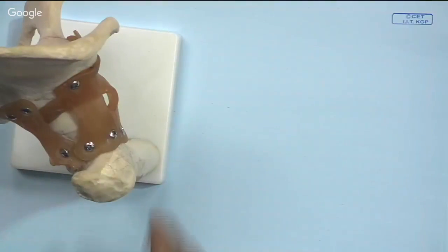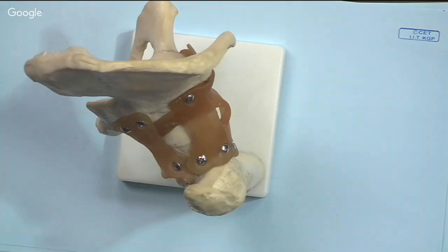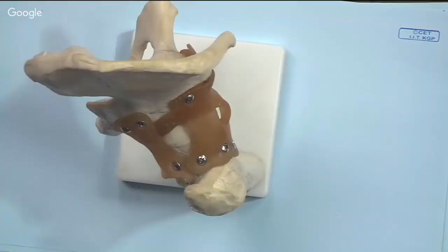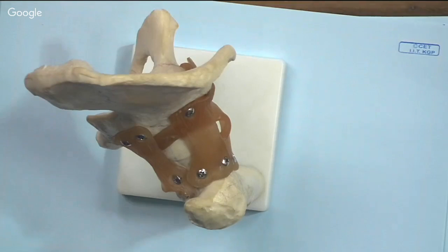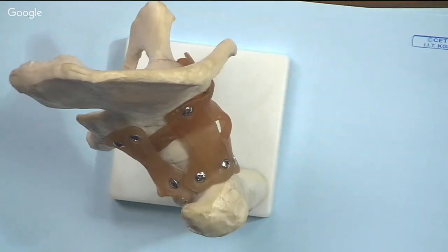Okay, so if you have a specimen like this, and then the spray, try to spray it from a distance, so that you don't actually generate a very thick layer of paint. It should be a very thin layer of paint, and try to be uniform, as uniform as possible, at least in the area of measurement, the area of interest.